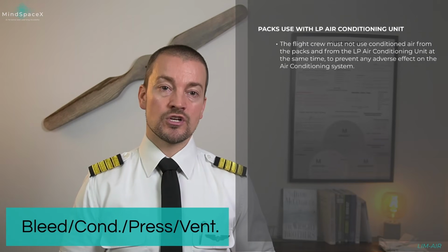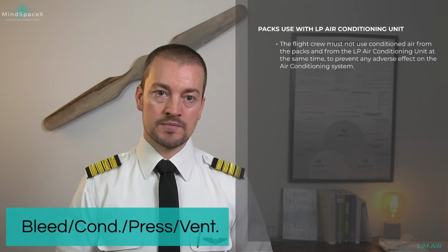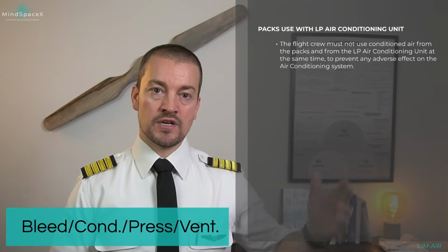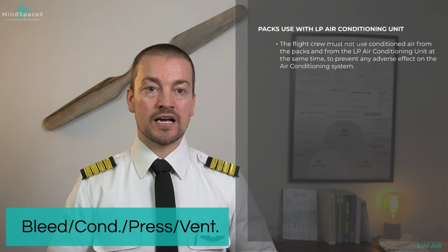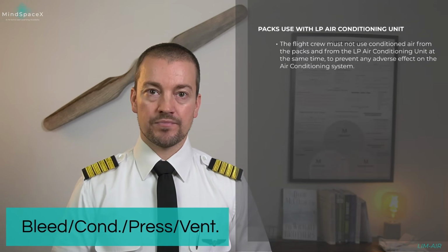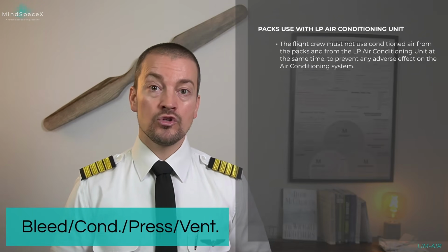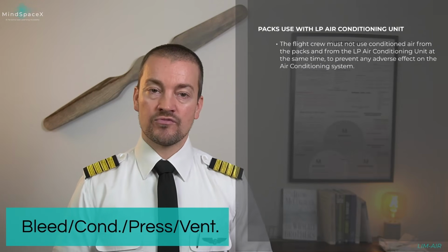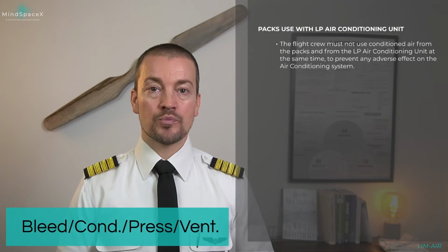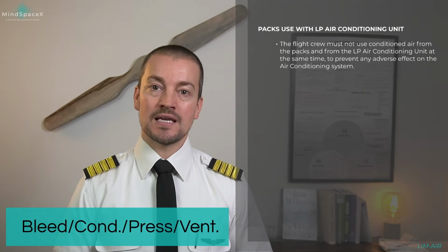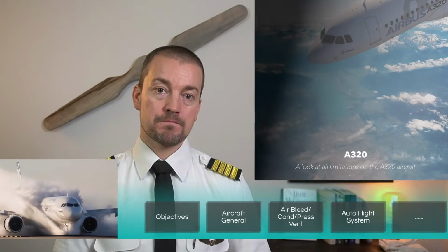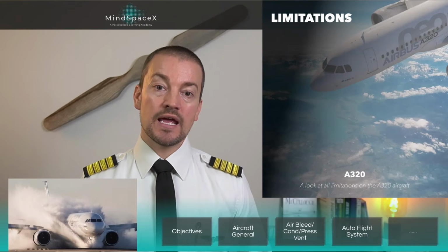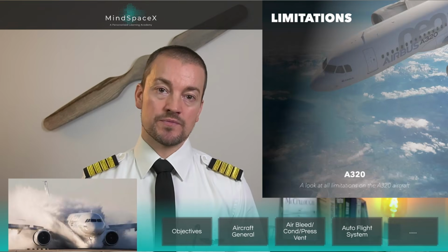There's also a limitation on using low pressure at the same time. The lower pressure, comparatively to the bleed, comes from the pack and the low pressure air conditioning unit on the ground. Flight crews must not use conditioned air from the packs and the low pressure air conditioning unit at the same time to prevent any adverse effects on the air conditioning system. And that was it on the air bleed condition and pressurization.